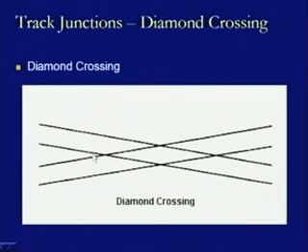So, this is one crossing location, this is another crossing location, both similar in nature, alpha being the same, and this is another crossing, and opposite to this there is another crossing, again these two are similar in nature, alpha being the same for these two. So, we will have 4 such crossings, and therefore we have wing rails provided at this location and at this location. These are the two locations where the wing rails have to be provided.